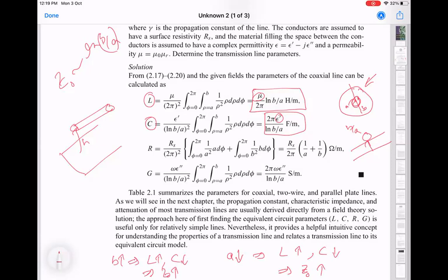So if you want to make coaxial cables of different overall dimensions and still have a 50 ohm transmission line, you have to adjust both A and B. So if I go from a thin coax to a thicker coax, then both A and B have to be changed in order to maintain the 50 ohm transmission. But that's going to be true for most cases.